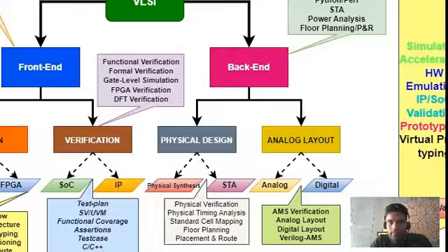Of course, we need to have some hardware description understanding as well. And scripting is important. Why is scripting important? Because when you do activities like pin mapping and pin planning, if it is a smaller design, you can do that on your own. And what if it is a larger design? You have thousands and thousands of pins. You have to map them to particular ports, and in that case, you can use a scripting flow, write the script, and through the script try to automate this kind of manual work.